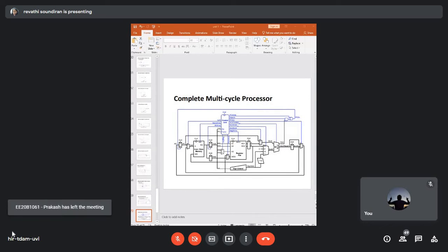So when you initially looked into your control unit, what we had was a main decoder, and we had the memory to register operation. Then you have memory write control signals. Then your branch. Then you have the ALU source. So these were the options with the main decoder of your 5-bit opcode. Next, you have the function code also with respect to the R-type instruction. Your ALU decoder had ALU controls.